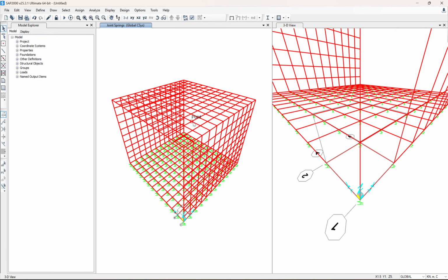Now it's 95% completed. One thing I wanted to highlight is that now the structure is there. We have applied the loads for the time being, but not all the loads. This is just to demonstrate how to model it from scratch. Once you do these things and have correctly applied loads, one more thing is remaining. If you see the vertical direction, yes, it does have springs, but in the horizontal plane, if you consider XY, it can move. We need to restrain it.